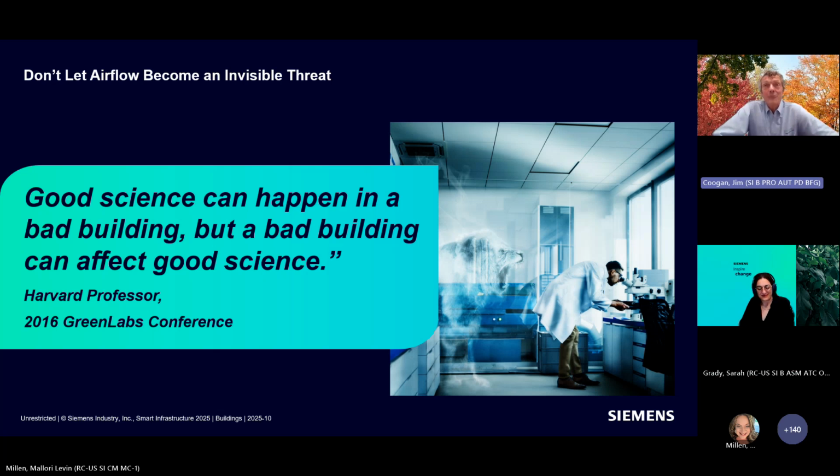I will add that the concept of demand-controlled ventilation, which can include occupancy-oriented changes, but also can include contaminant sensing variations. If you're using either one, you have to stop and think, how well do my sensors actually tell me what's important here? We talked about how your occupancy sensor may tell you the people are gone, but maybe the hazard has continued. That's a case where you're sensing the wrong thing.